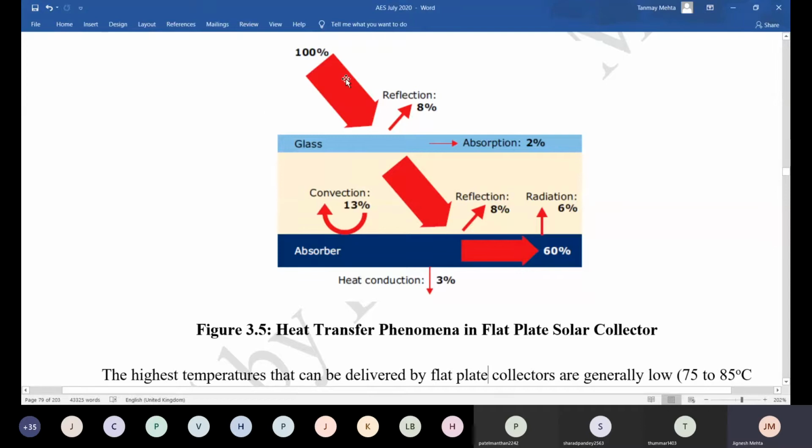It comes in contact with the glass. Now on the outside of the glass, there is air flowing over it. It's wind, which may have high or low velocity, but you can always say there is some velocity attached to air, which is called wind. Because of that, on one side the heat is supplied by this hot air. It has to pass through the glass by conduction, and finally it comes to the outer surface. If you touch the outer surface, you should feel it hot, because its temperature is higher than the ambient temperature. So air takes away heat from here.